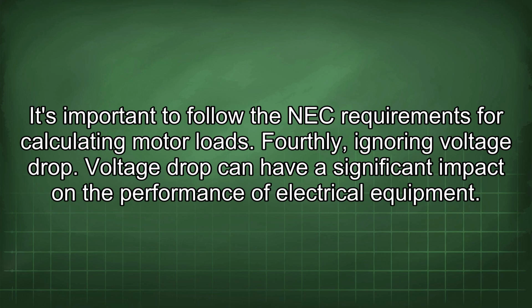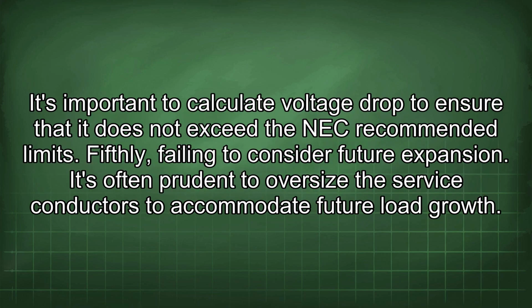Fourthly, ignoring voltage drop. Voltage drop can have a significant impact on the performance of electrical equipment. It's important to calculate voltage drop to ensure that it does not exceed the NEC recommended limits. Fifthly, failing to consider future expansion. It's often prudent to oversize the service conductors to accommodate future load growth.